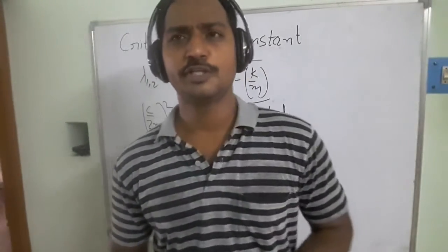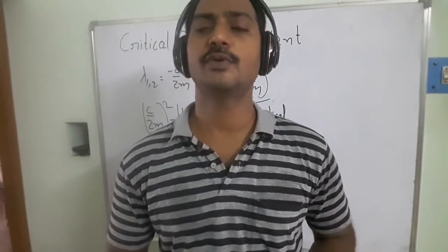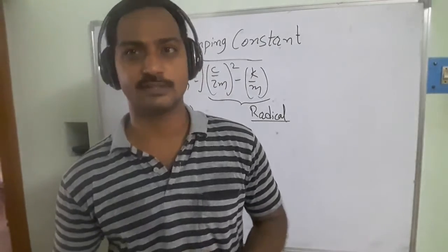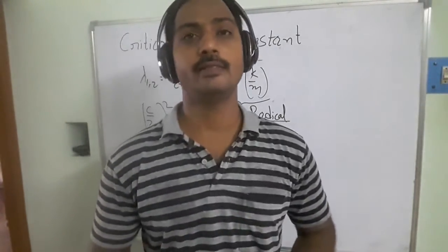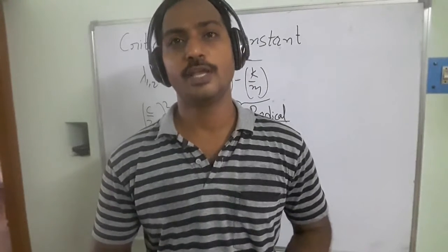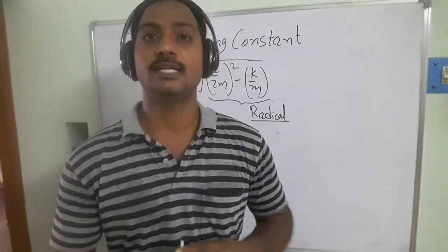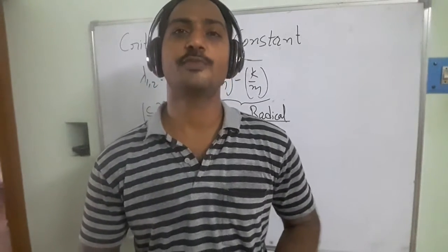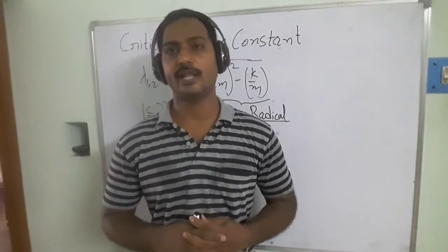Welcome back to the video lectures of mechanical vibrations. In the last video lectures we derived the equation for free damped vibrations, the characteristic equation. From that we determined the displacement of the vibrating system, on the assumption that the dissipation of energy takes place in an exponential way. The vibrations of the motion are going to die out exponentially. On that basis we derived that equation.